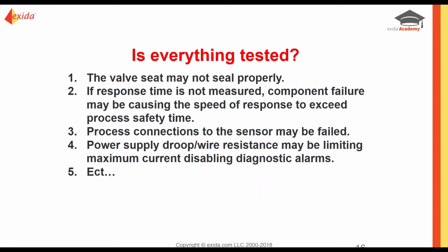Let's say, for example, we have a pressure sensor, and we're going to isolate it and we're going to pump it up so that the sensor pressure exceeds that trip point. You have a remote actuated valve and you actually observed that it moved. That's more of a proof test than a lot of people do. A lot of people would say, well, it's remote actuated, I'm not going over there. I saw that it will trip, that's good enough. So let's say you went and you saw the valve move.